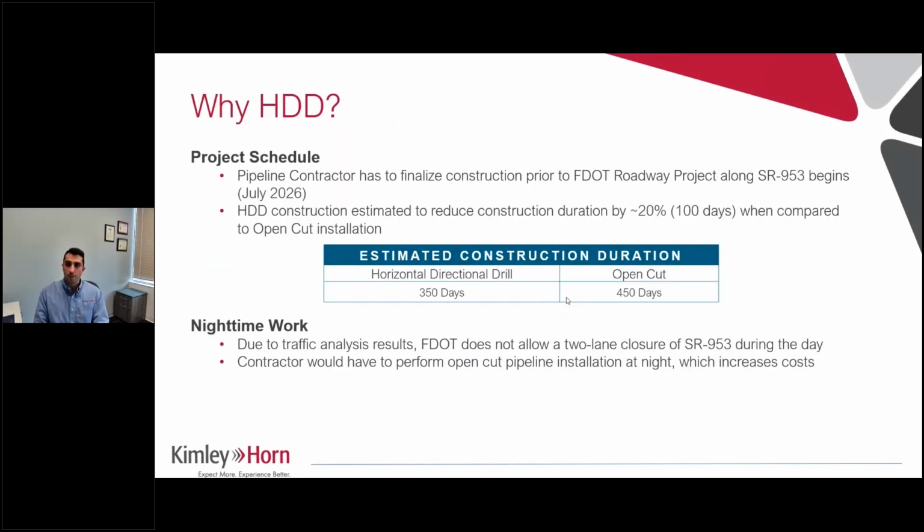So why are we going with directional drills? The main reason for this is the project schedule. We're working on a state road where in 2026, FDOT, the Department of Transportation, will be coming in and doing their own mill and resurface job for the entire corridor.